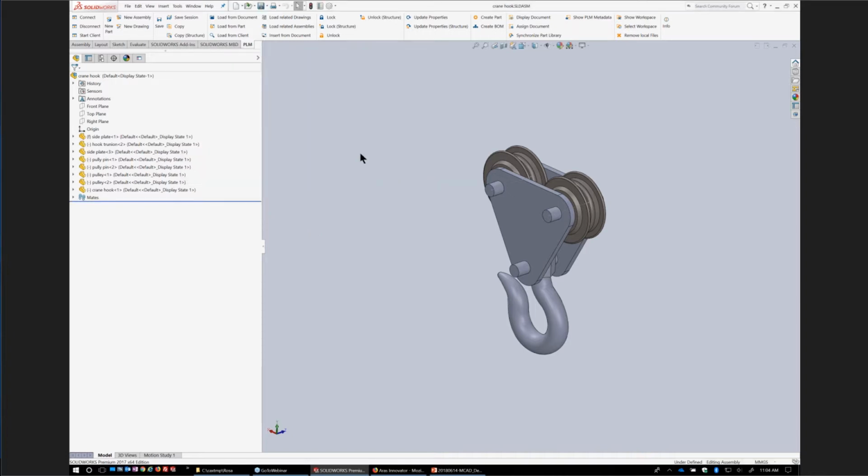In the process of storing CAD data into Aras, the process is really simple, utilizing a CAD connector. In our case here, I have an assembly and I'm finished with my design and I want to start to put that information into Innovator. Our connector is built to be embedded inside the CAD tool, and you'll notice on my toolbar I have the PLM connector for XPLM enabled, and I'm simply going to hit the save button. It's going to ask me to log into Innovator, and I'll go ahead and accept those and log in. And then the process begins.